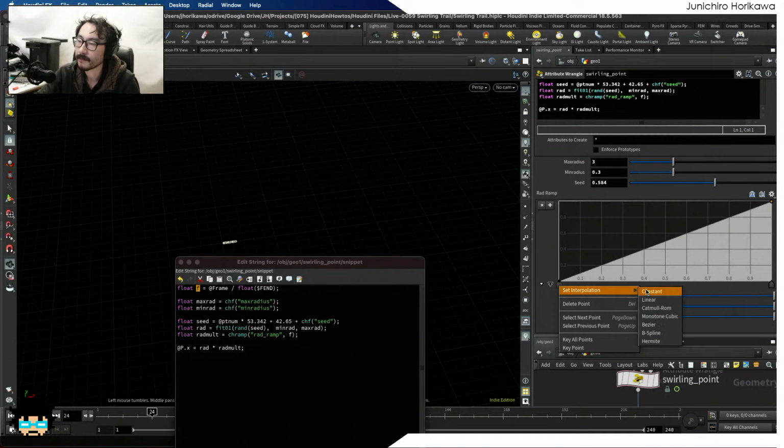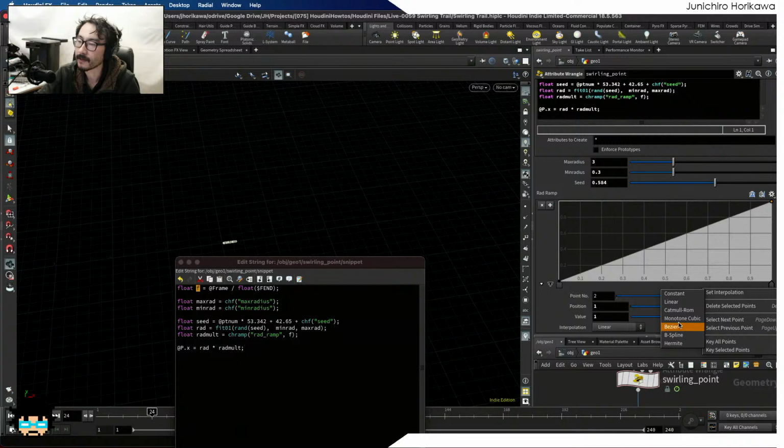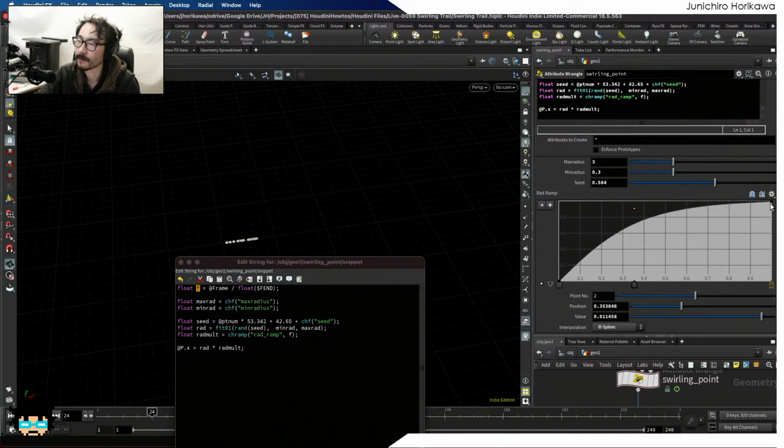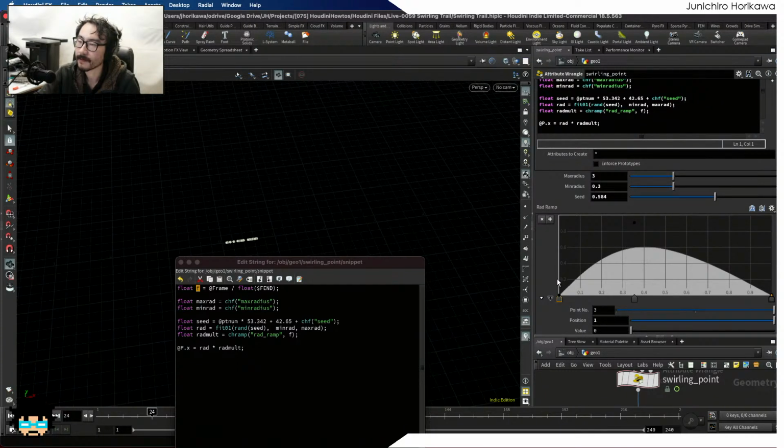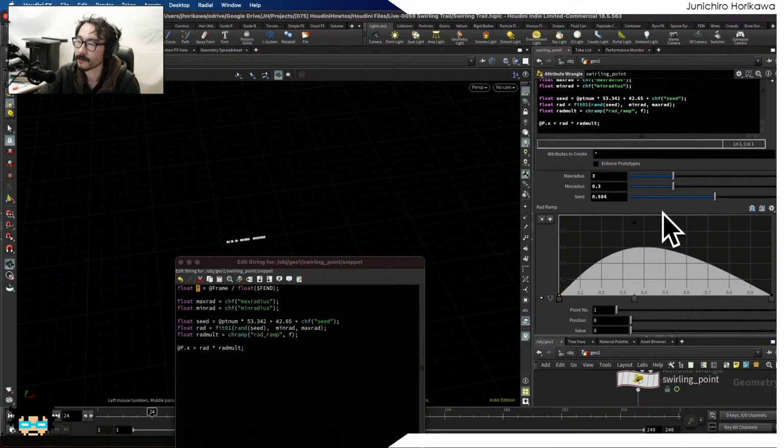First I'm going to convert it into a B-spline for each end so that it will be a smoothed curve. Now this y-axis indicates the point positions in terms of this radius. Okay, so if it's 0, it will be at 0, 0, 0 positions. If it's equal to 1, then it will be at the steady state positions. So I do need to have a steady state position for some range, and I do need to move this point slowly from the center and go to the steady state positions and go back to the center.